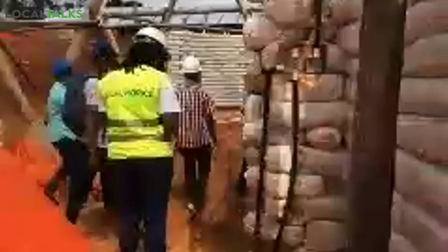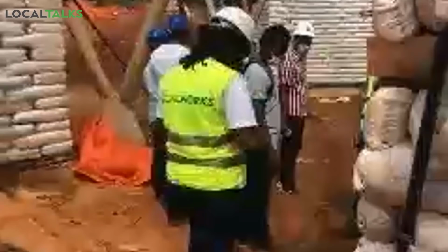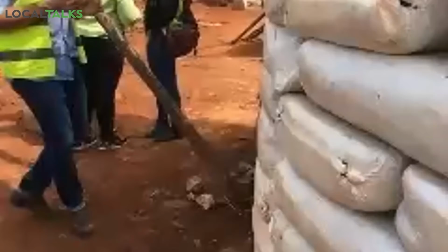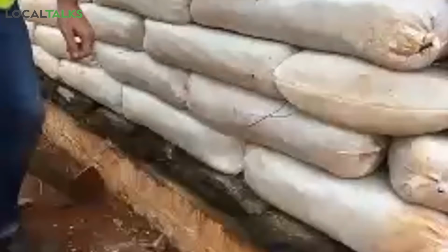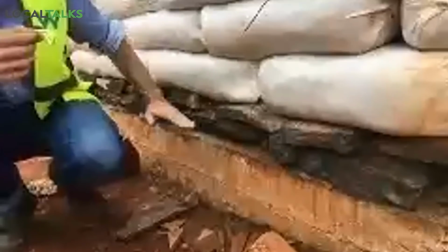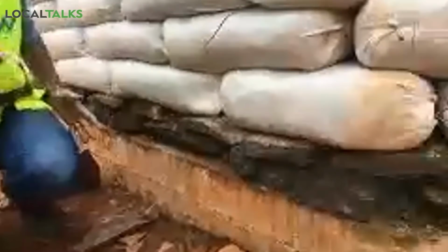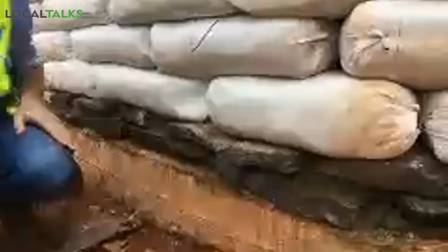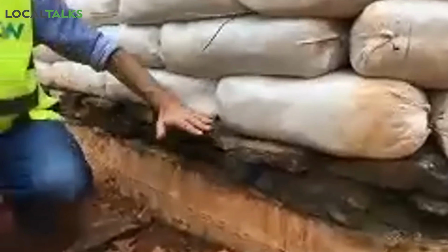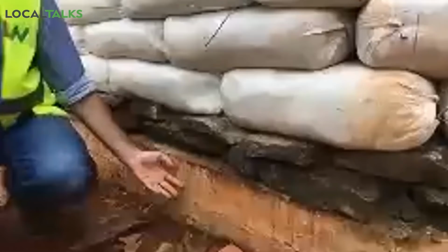This is a good area to study our so-called stone DPC. I don't know whether everybody heard the explanation that Edson made at that stage, but this is a very hard, local granite stone that we have applied there in 3 layers, 3 thin slates, sometimes 2 if the slates are a bit bigger. The primary reason is obviously that we don't want moisture to rise through the wall.